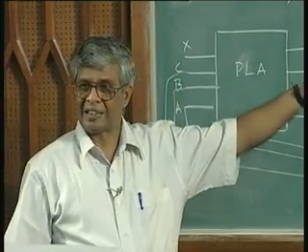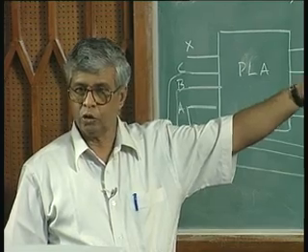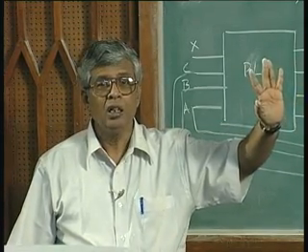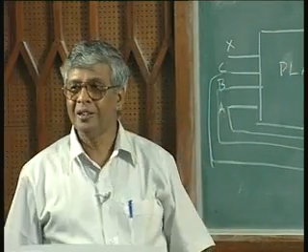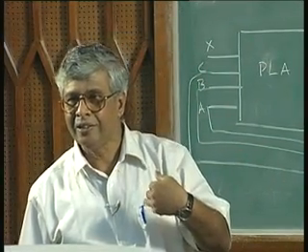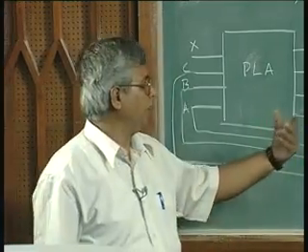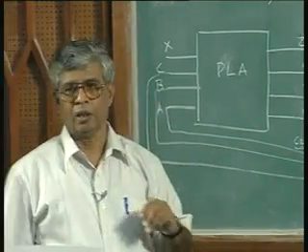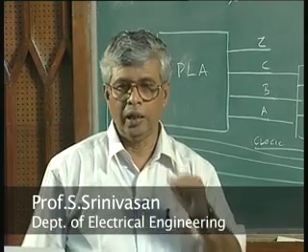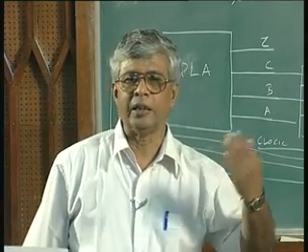Each of those 4 columns you have to minimize with as many common terms as possible. Then come out with a list of product terms you need to generate, generate those product terms and combine them with the OR gate. And then you can use a programmable array logic also, we will see how to do it in the next lecture.